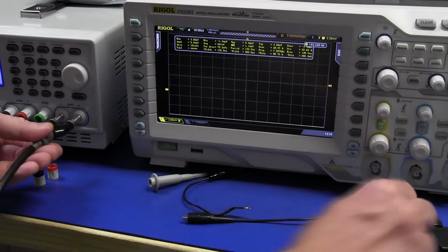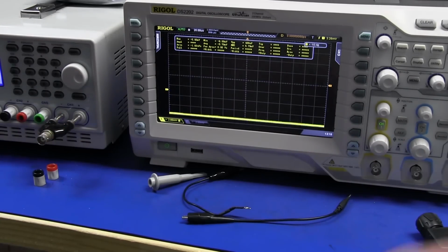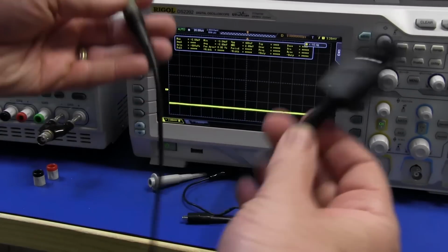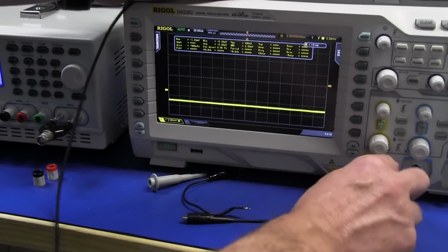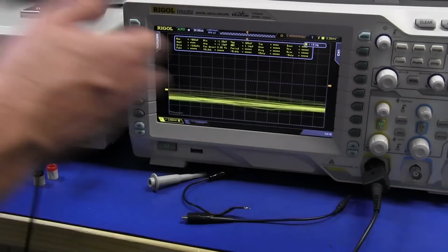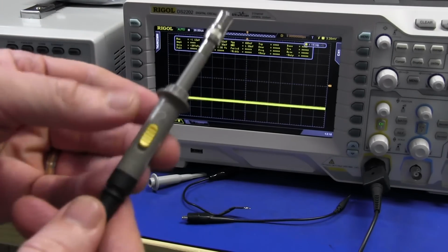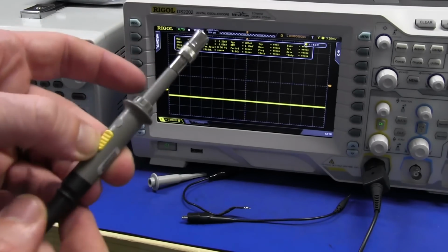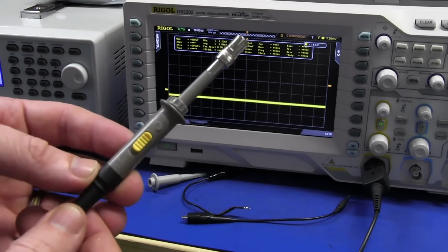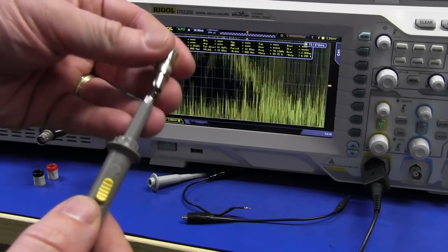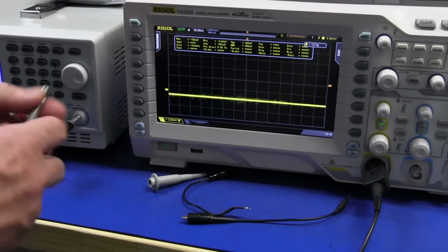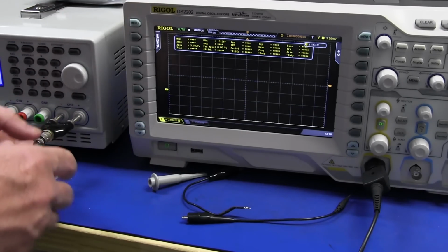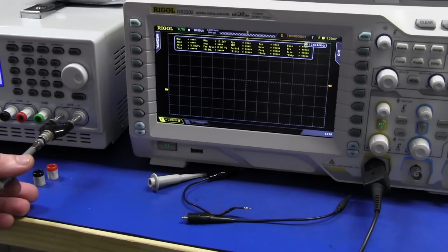Now, if we disconnect that and we plug in our proper scope probe, this is the 350 megahertz one which comes with a Rigol, and it's got a ×1 ×10 switch, so we'll put it on ×1, so it's operating just like a regular coax, and I've got this little coax adapter. It's a bit loose, so please forgive me if the connection is a bit intermittent there. I may have to hold it. There you go. Look at that.